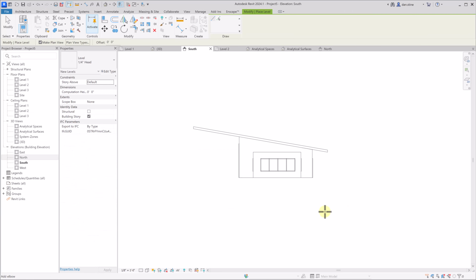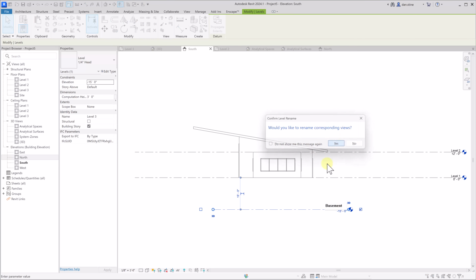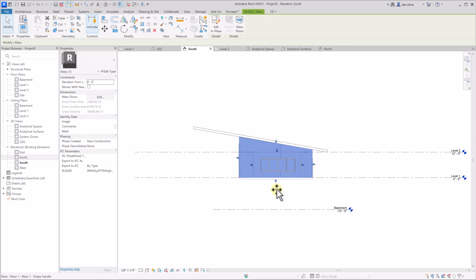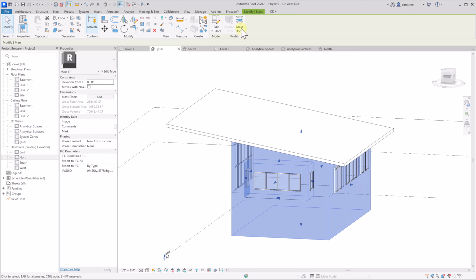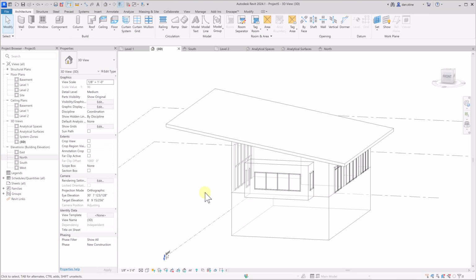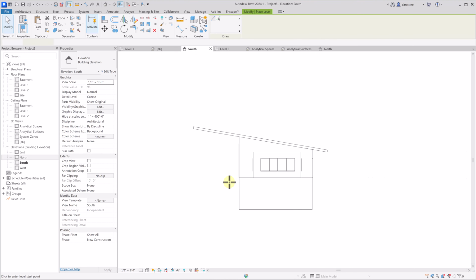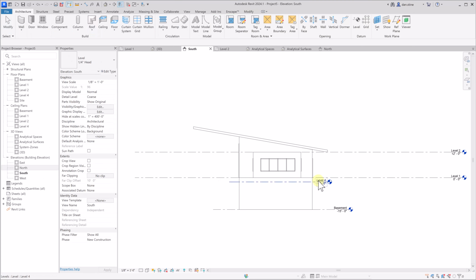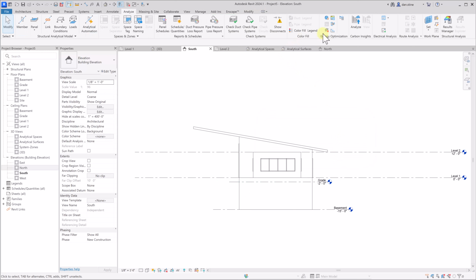And then just to take this a little further, I'll show an example of a basement. So I'm going to create a level, call it basement, and simply pull the bottom of the mass down to align with the basement. We need to make sure we add the mass level for floors. And then we'll actually add a level that defines the grade. So we don't want that main floor to be a slab on grade.